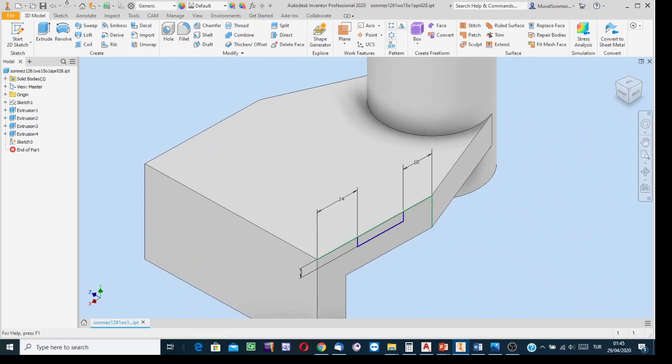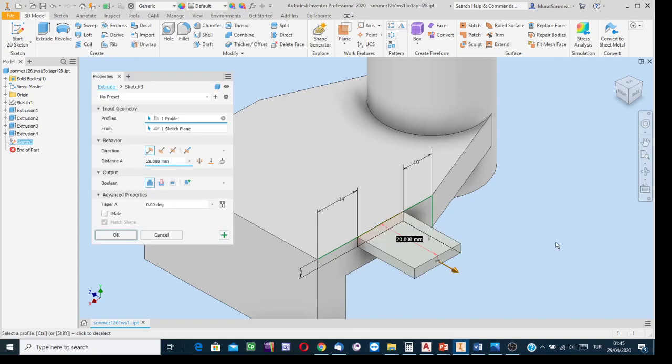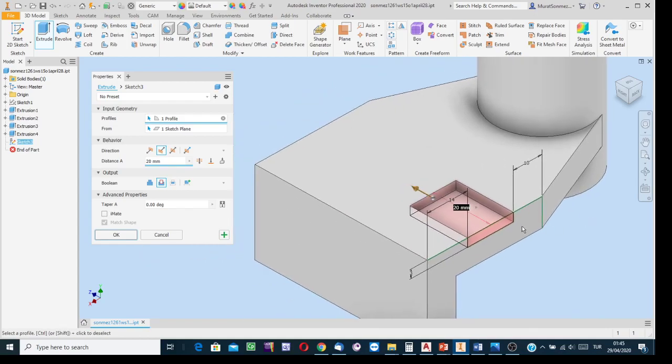And then now the rest is the cutting process, extrusion, okay? Now Inventor is offering a material heading, no, it is a cutting issue. So select the cutting option. And then how many millimeters is the cutting depth? If you want, you may hold the golden arrow and then simulate the cutting process. Assume that a crank shaper is removing the material.